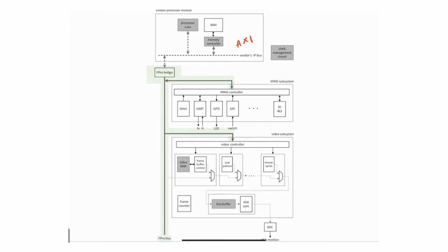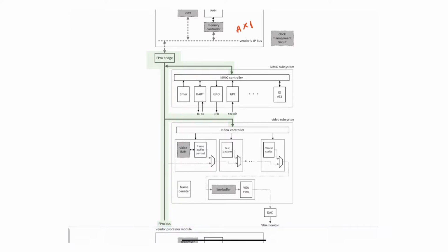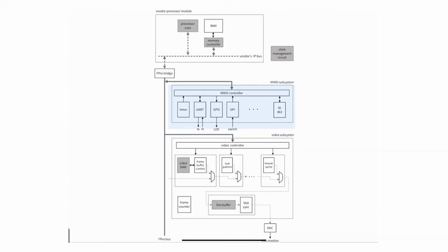All right, so moving on to the next subsystem. The SoC that we have, we're going to develop it with two subsystems. You can have it with as many subsystems as you need, but I'm just going to introduce one called an MMIO subsystem, which is a memory mapped IO subsystem. That particular subsystem has a bunch of slots that you can actually put whatever you want in. And specifically, for the sake of consistency, we're going to have a very specific number of slots, and these are 64 slots. So you're going to have from 0 all the way to 63.